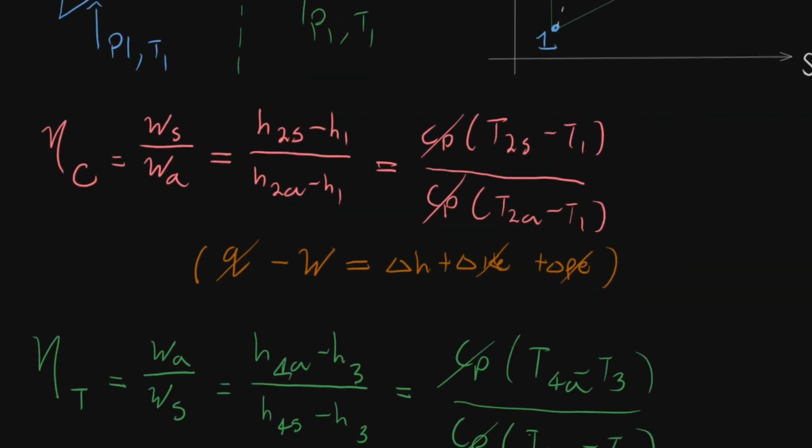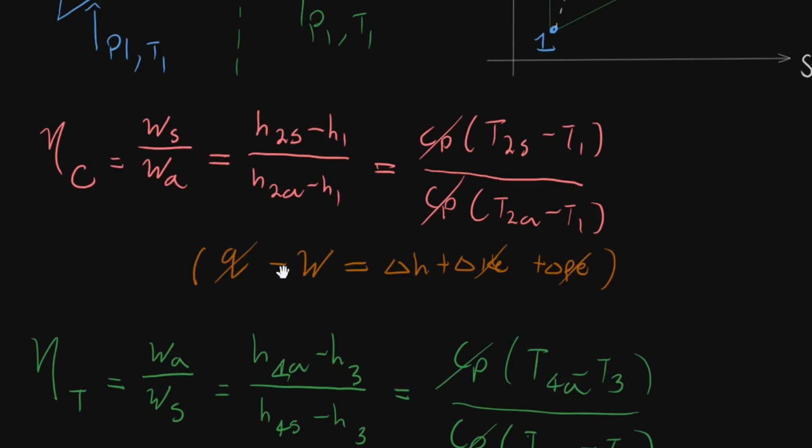This is just an energy balance, right? We'd have heat input minus work output equals our delta H plus delta KE plus delta PE, and I guess not of the system. This would be between the inflow and the outflow because we're looking at steady flow. Should be a little bit more careful there. And we're assuming it's adiabatic, which means that our W would be our delta H.